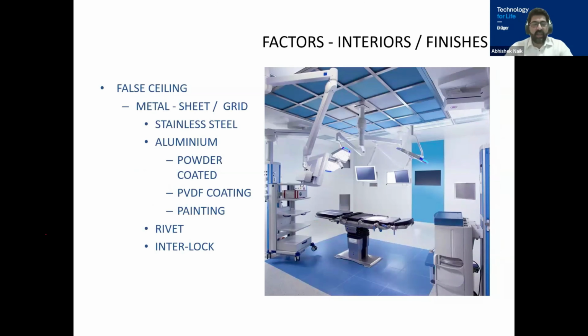Okay. Ceiling, what do you recommend? Ceiling, again, generally we prefer GI because the capex requirement of the OT should also be balanced. So we recommend a galvanized iron ceiling with an antibacterial powder coating. There is another option, if you want the entire OT to be of stainless steel, especially in coastal areas, on a seaside, where the sea air can cause damage to your operation theater. In that case, we recommend that even the ceiling should be stainless steel with a powder coated variety.